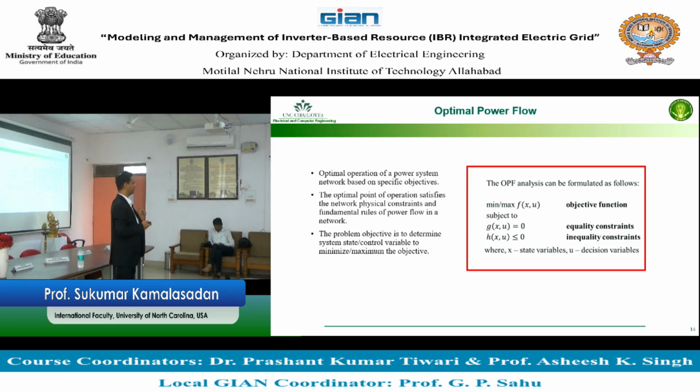That constraint is generally called thermal constraints, which means the power going through the network should not go as heat. So that's basically what we consider thermal constraint. So is that the only constraint on the network? May not be the only constraint. There could be constraints with respect to voltages at points on the network. So that voltage constraint needs to be honored.